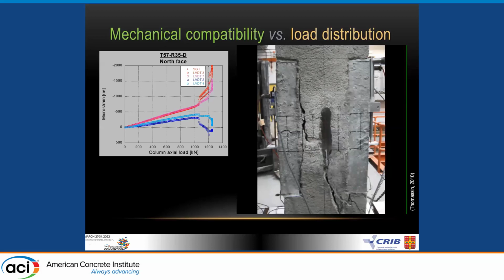So in this case, it was 5,000 KSI elastic modulus repair material versus 3,300 KSI elastic modulus concrete. So much stiffer, the repair. And this is the only combination where we got that behavior.